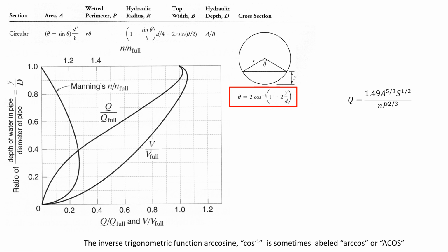So when the pipe is half full, you don't get half of the flow rate. You only get 42% of the flow rate. So it's a nonlinear response. If the pipe is 10% full, it's not 10% of the flow rate because the ratio of the wetted perimeter to the area is so far in the extreme. So that's why this is not a straight line.